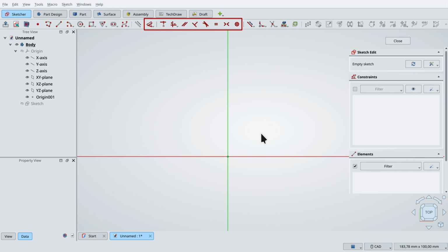These are used to fix and anchor your sketch, preventing it from moving or breaking when your model recomputes. This is a critical part of the process, and these tools can be a source of frustration if not used correctly. After that, we have the edit tools for operations like trimming unwanted lines, creating fillets, projecting external geometry, or making offsets. Finally, the last few icons are visual tools related to splines, which won't be necessary for our demonstration today. Let's look at a concrete example.